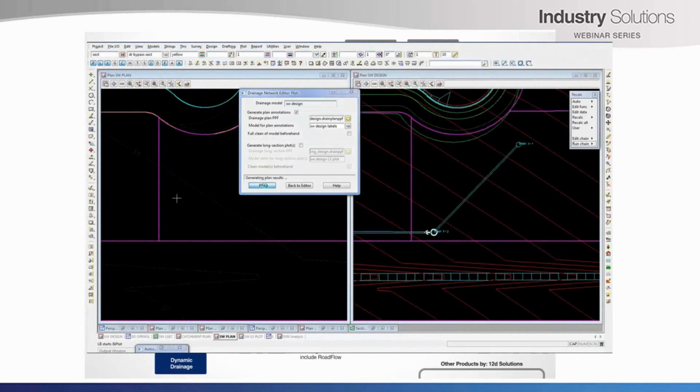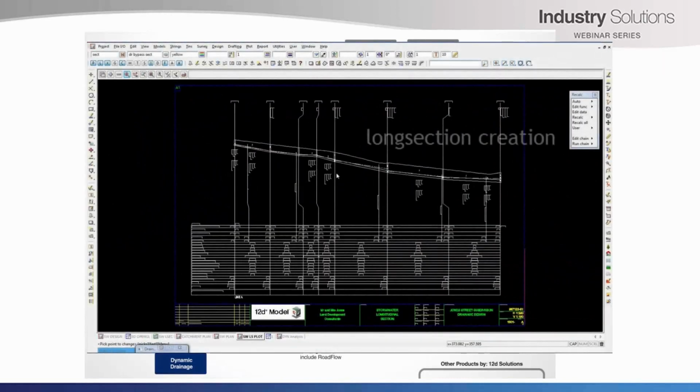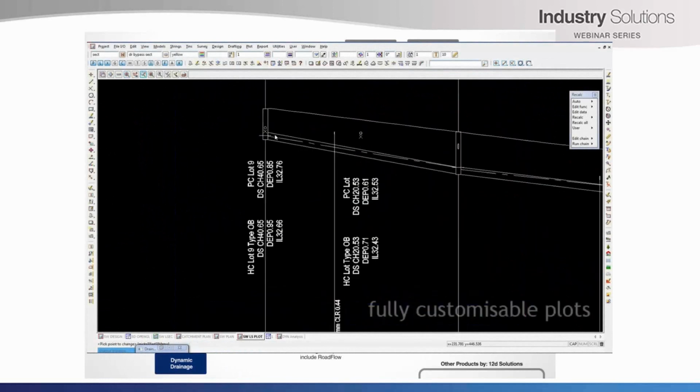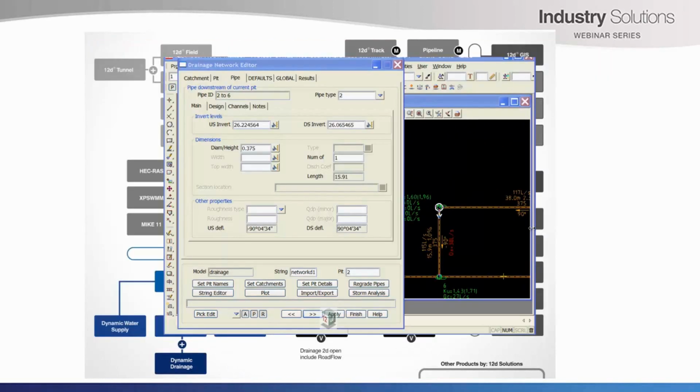Clashes with other drainage networks or services are managed for the network, with clashes reported and modifications suggested in problem areas. The network can be reported for pit schedules, pipe schedules, and excavated quantities can be tallied. Drainage design can be simple or complex as the project dictates.